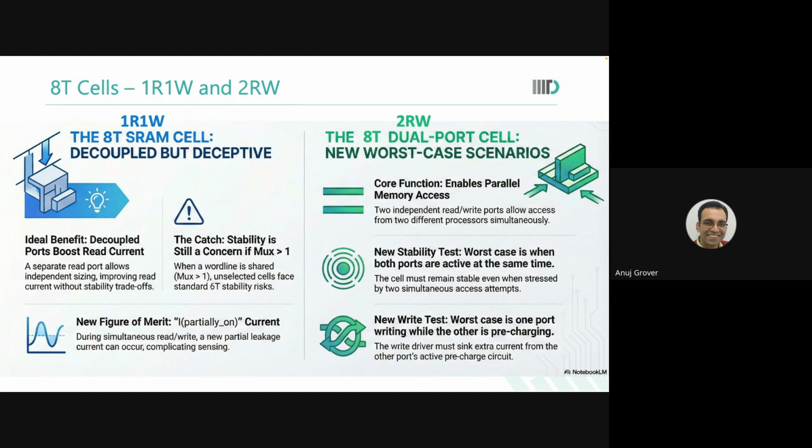So what are the two-port constraints, and why are two ports actually slower than the single port? We're talking about it in terms of a one-port access kind of range. Madhav, okay, so when we look at the self-timing part of it, which we discussed, that reset comes or SAEN comes. Now, SAEN arrival: I'm accessing port A. At port A, do I know whether port B is being accessed or not? I'm on one side of the memory. Port B may or may not come.